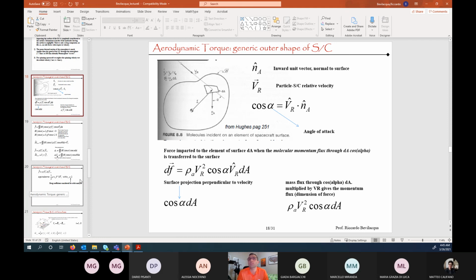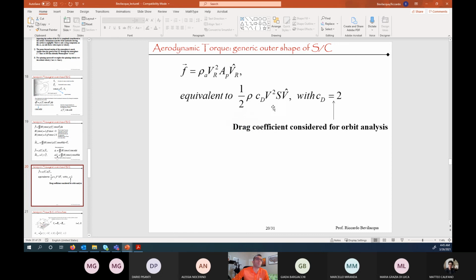Yeah, so that would definitely make it more difficult. But these are the developments; the reality is that in practice, this is what we want to write. This is what people write for the drag force and then, of course, for the torque as a consequence. What we try to do is, well, the velocity is what it is: the velocity of the spacecraft through the atmosphere. And then rho, we want to keep as the atmosphere at rest value, so it's the environmental density, and then all the things that we talked about that we need to model will be captured by the CD.